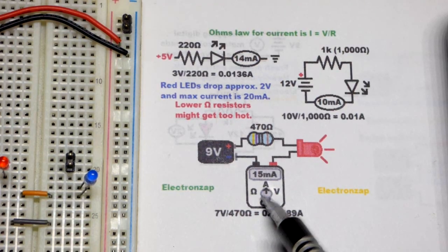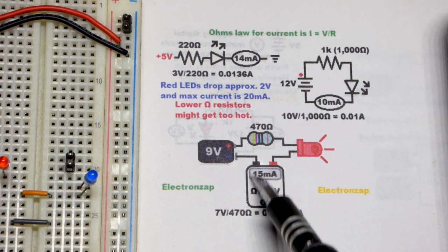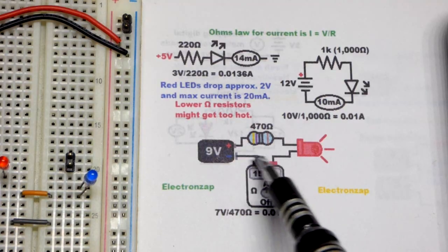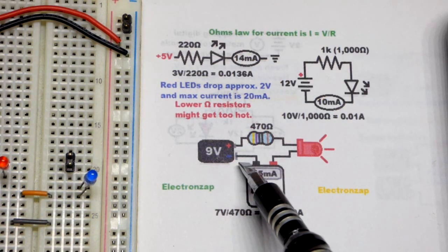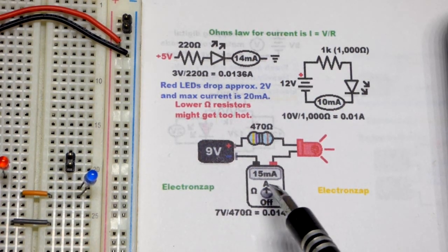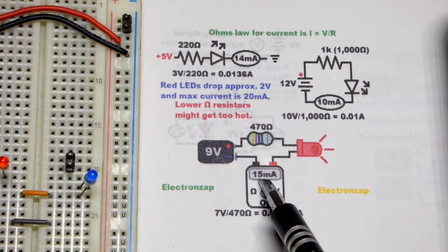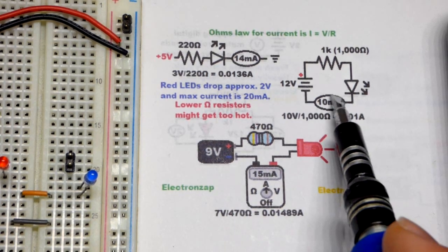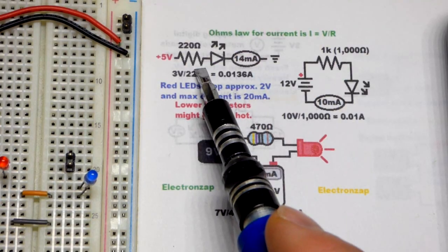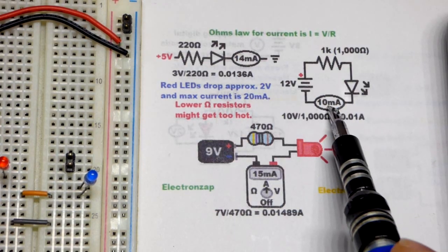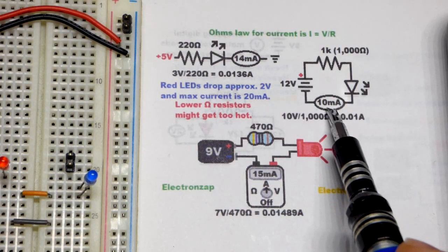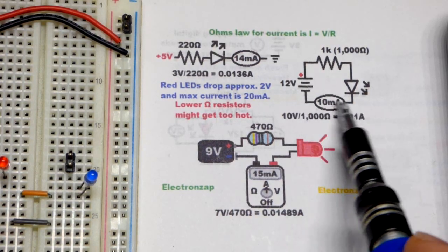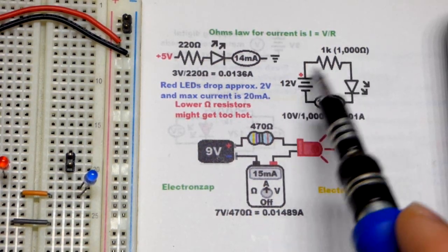Now, the multimeter that I drew here has to let that current flow through the meter. You have to make sure there's a gap in the circuit, and then you complete it through the meter right there. It's going to be about 15 milliamps in that range, as you can see right there, after you do the math, if you choose to measure it. But in any case, we have a pictorial. Usually you'll see circuits in schematic form right there. Usually they won't show the current that's flowing through, but that's all this is telling you. This is about 10 milliamps of current flowing through the circuit right there.